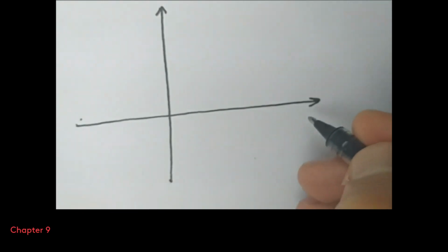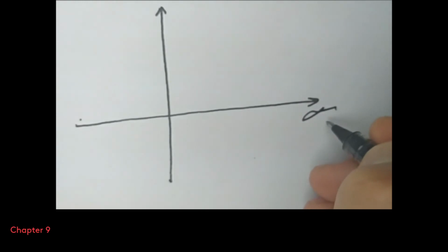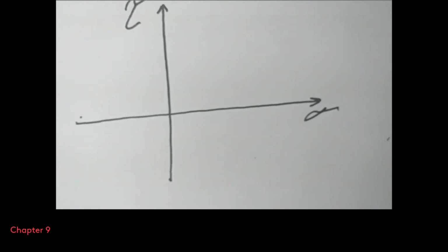Now at a point I have three stress values: in the case of a plane stress, two normal stresses and one shear stress. So I begin from a point and hypothetically assume that sigma x is bigger than sigma y.